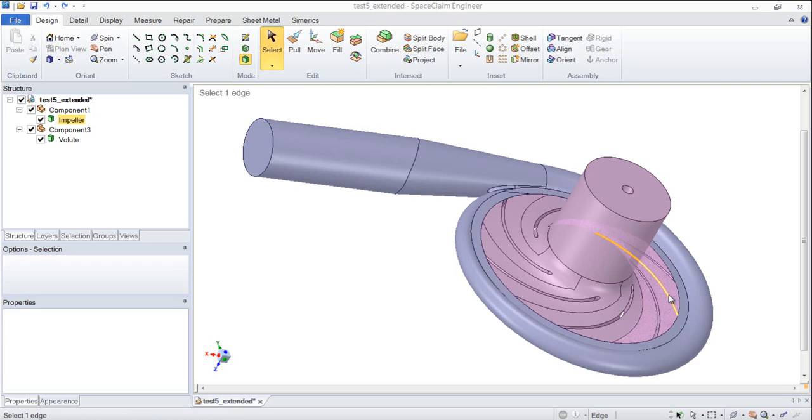This is the liquid volume, which has been split out from the solid parts like the pump housing, impeller blades, and so on. Before we go over into PumpLinx, we can take advantage of some of the features in SpaceClaim to make the model setup easier in PumpLinx. If we name the surfaces that require boundary condition specification here in SpaceClaim, then we can skip the surface preparation steps in PumpLinx. So the components to our model are basically this.